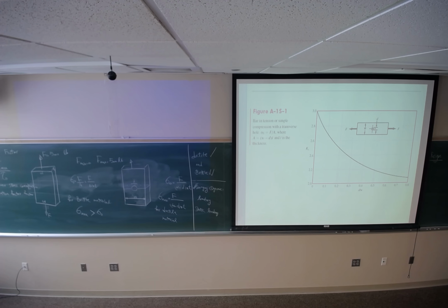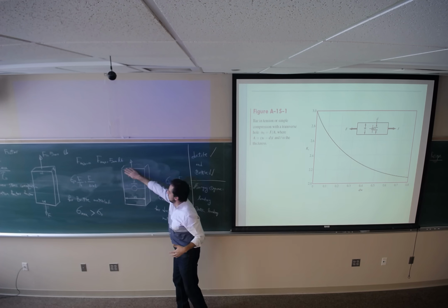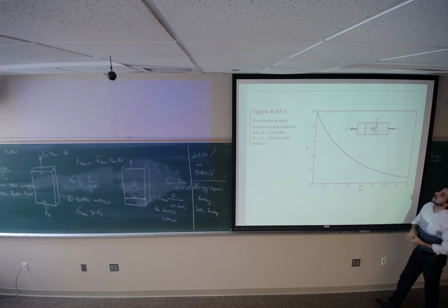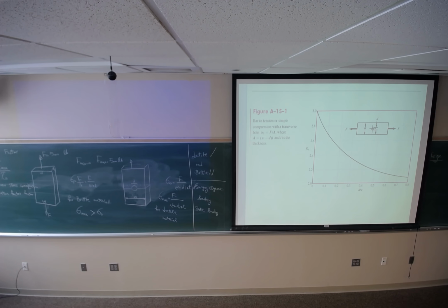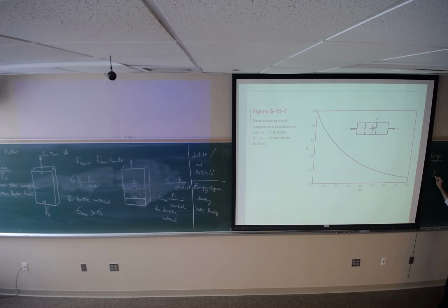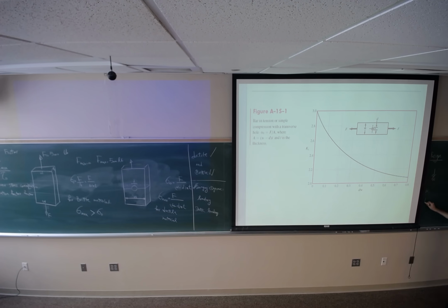some standard configurations. Here we have something like this. If we have a rectangular cross section with a hole at the middle, which is under axial loading, what would be the KT? On this axis, you will calculate D over W. W is this thickness, and D is the hole diameter.